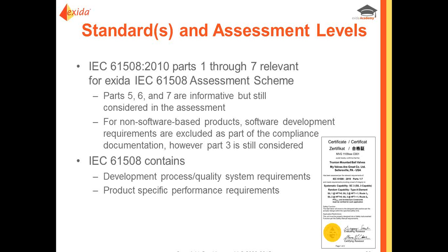We do our certificates and assessments for parts 1 through 7, and that's all relevant for the IEC 61508 assessment scheme of exida. We've had people ask, well, parts 5, 6, and 7 are informative, why do you count them? Well, they still have valuable information in them. So we still make sure that parts 5, 6, and 7 are considered in the assessment.